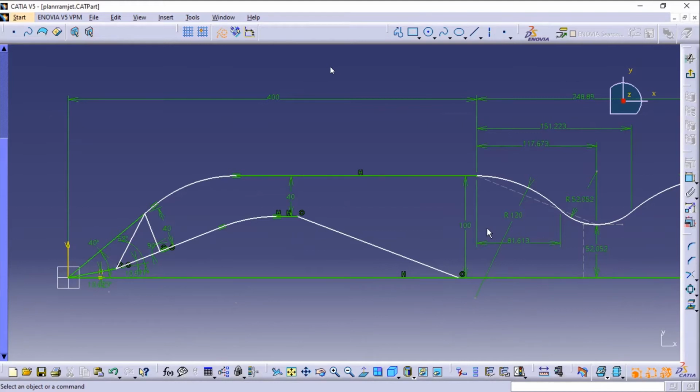So I changed this area because it depends on the Mach number. If the Mach number in this region 4 is too big, I think there is a problem with this equation. So I changed this area, but the relation between these two areas shouldn't change, or the properties in the inlet of area 3 would be different. So I have to calculate the properties here too. So what I did was the area changes along here, but is the same at this point.